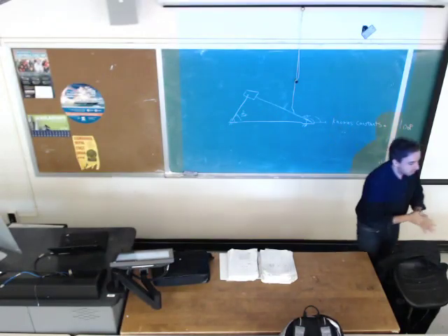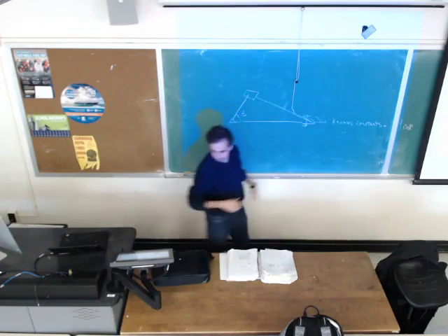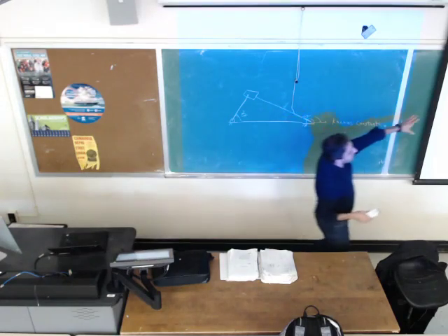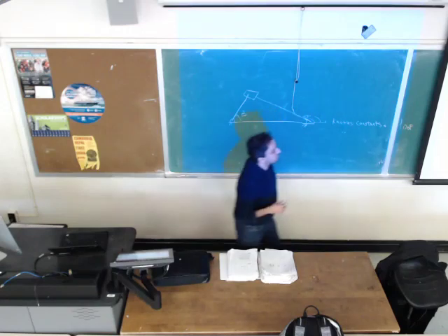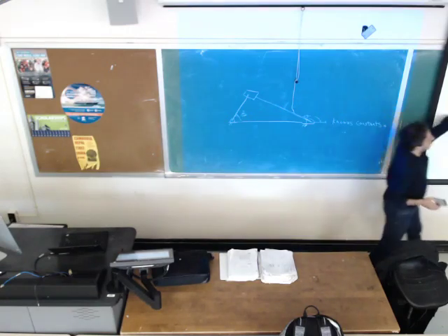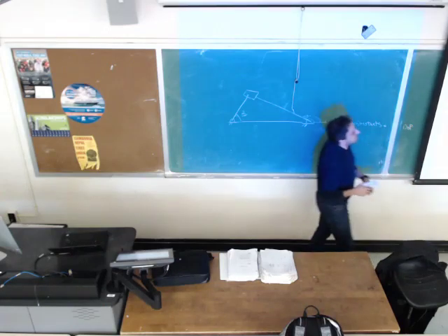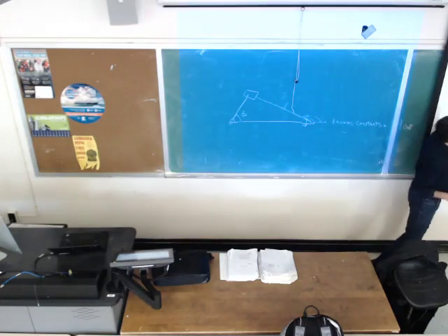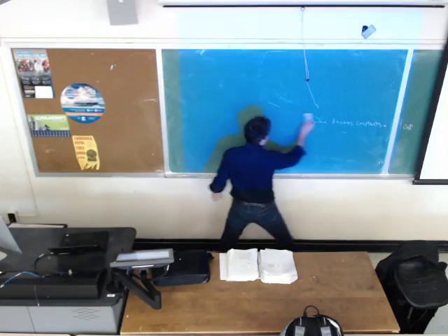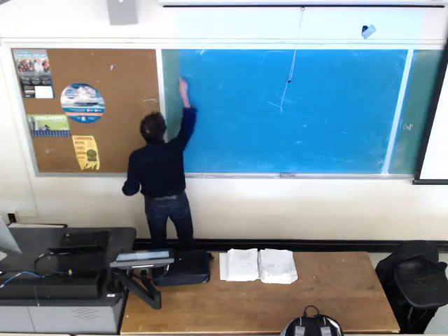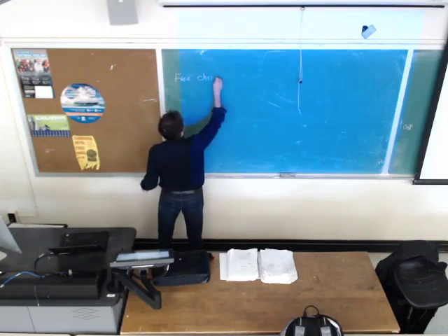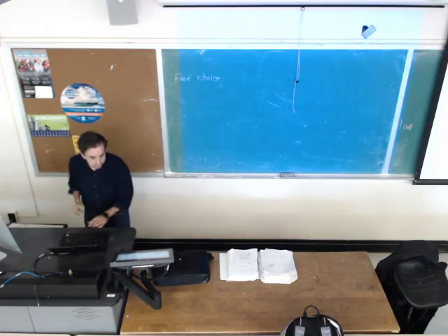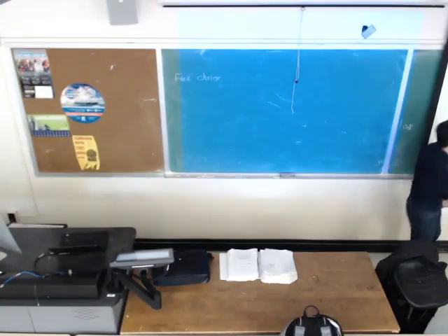Good afternoon. So let's continue on the Freudenstein method. We have done function generation for the 4-bar mechanism. We would like to design a synthesis mechanism such that it generates this given data. But in this method, the three choices that we pick were beta 1, 2, and beta 1, 3.